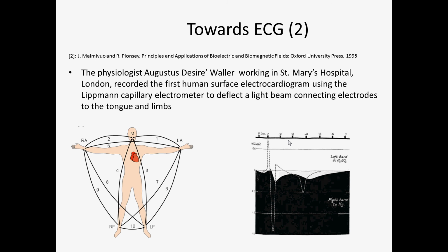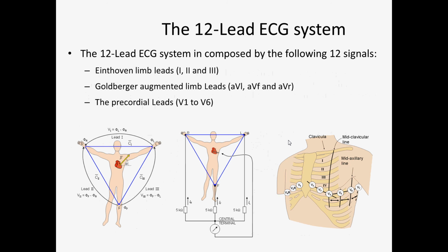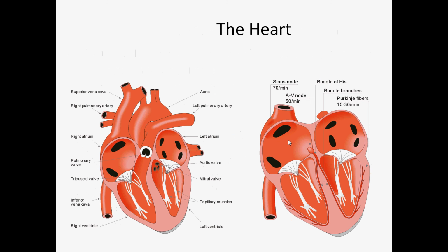And the first ECG device needed to have electrodes on the tongue. Not very pleasant, because those electrodes are actually big pliers. Why? Because we needed to achieve very low contact impedance, because the input impedance of the amplifier at the time was terrible. Now we use a different system. There are different models, representations of the volume conductor of the heart. Not going into much detail of that.